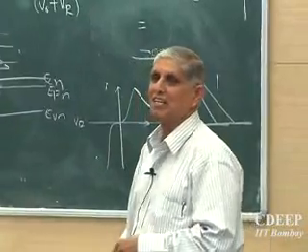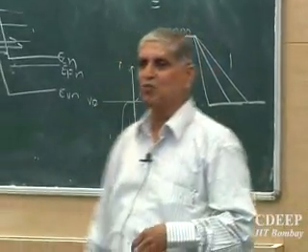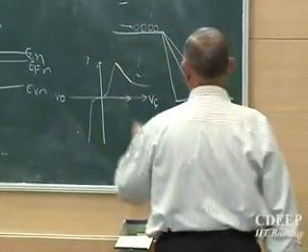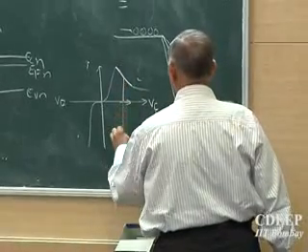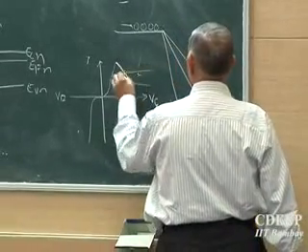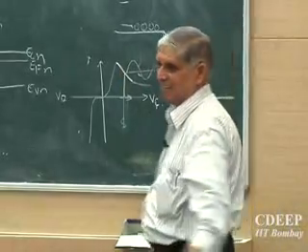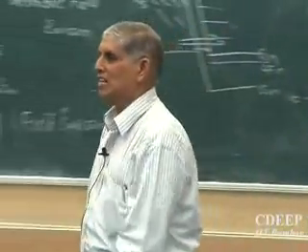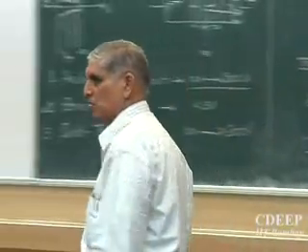Such a device can therefore, instead of dissipating, generate. These are used for oscillators. Okay. So if I bias here and apply a signal, I will see a larger signal on this. These are called tunnel diode oscillators. So negative resistance leads to oscillations.